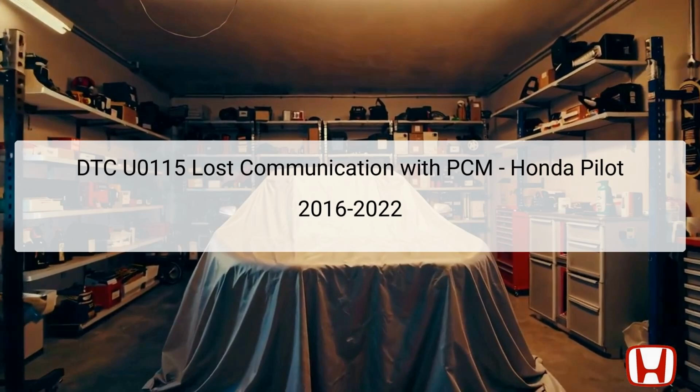The Diagnostic Trouble Code, DTC U0115, indicates a failure in communication between the Powertrain Control Module, PCM, and the Transmission Control Module, TCM, in the Honda Pilot. The PCM is responsible for controlling engine functions, while the TCM manages transmission operations, both of which are crucial for the vehicle's performance.